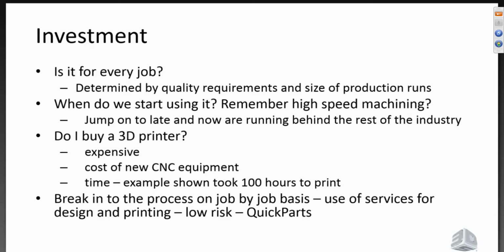The production volumes may be such that you're not going to see, down at the end, a return of that money. And it may be that the quality is not so big a concern. However, if the part does have major quality concerns involving warpage, or if there is a significant reduction of the overall cooling time such that it reduces the overall cycle on a big production run, you may be throwing money away by not doing it. So it's a decision to be made based upon the job, or upon what the customer dictates is necessary for the quality of the part.